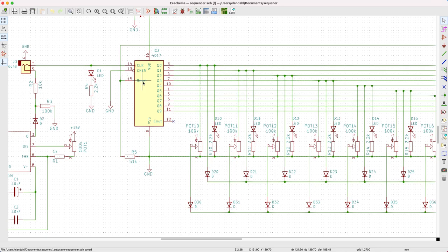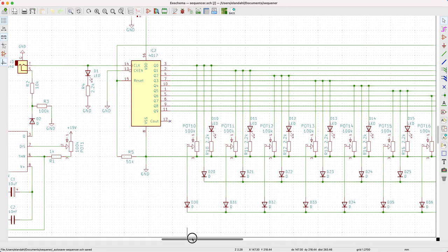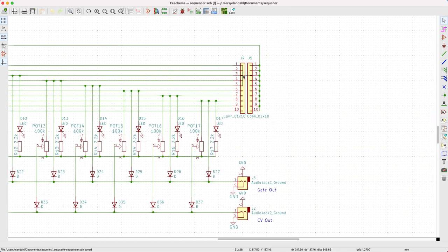So just as I demonstrated in the videos, if I only wanted the first, say, 3 lights to fire in sequence rather than go through all 8, I would jumper across number 4 here, and then by the time I hit light 4, it would reset and then jump back up to the first LED.